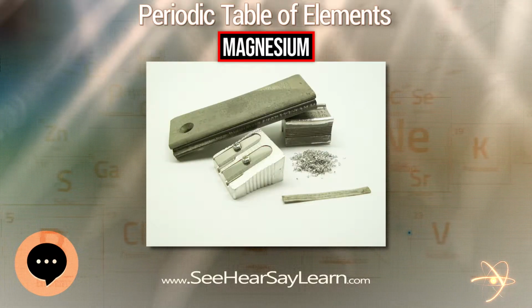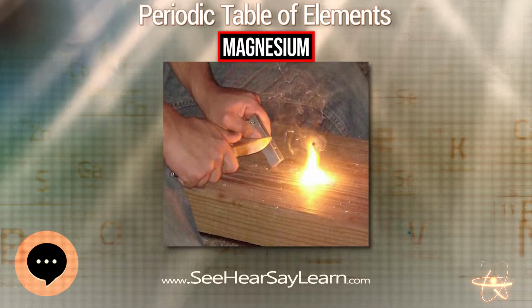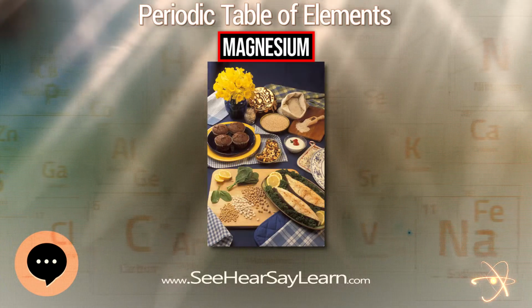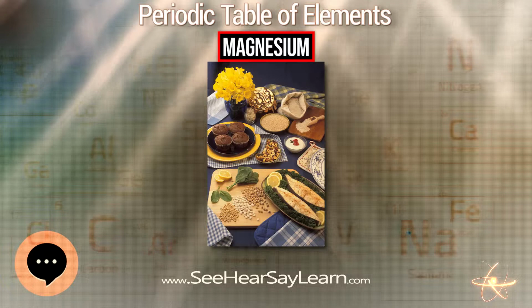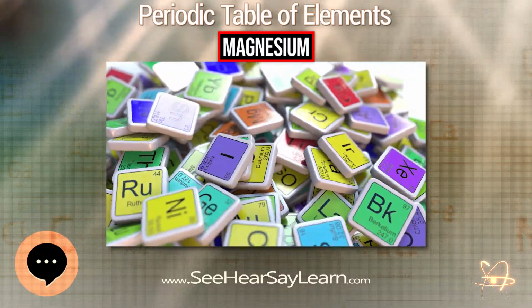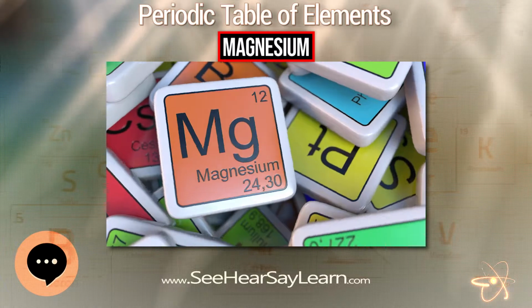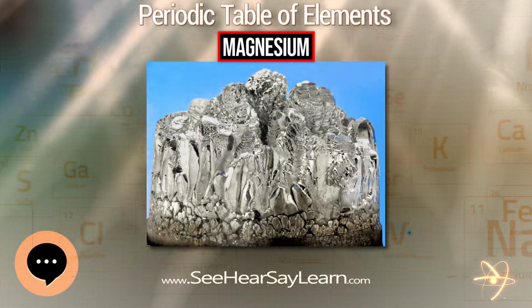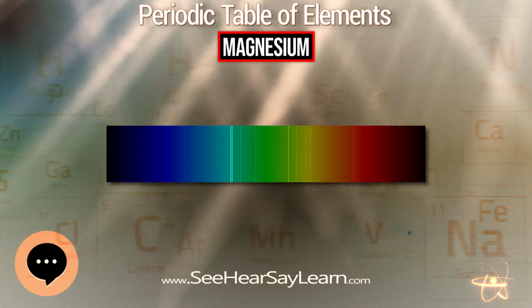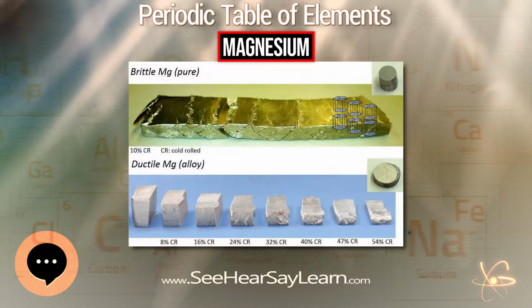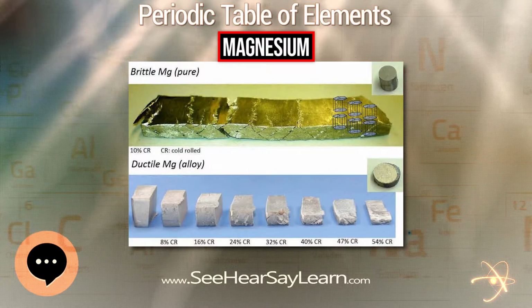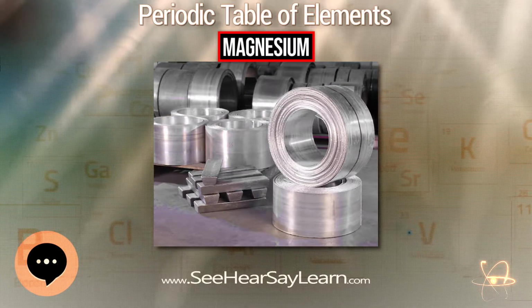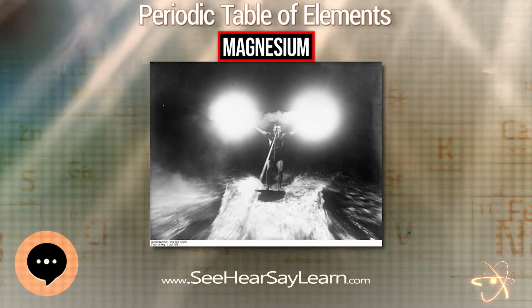Currently, magnesium alloy use in aerospace is increasing, driven by the importance of fuel economy. Development and testing of new magnesium alloys continues, notably Electron 21, which has proved suitable for aerospace engine, internal, and airframe components. The European Community runs 3 R&D magnesium projects in the Aerospace Priority of 6 framework program. In the form of thin ribbons, magnesium is used to purify solvents, for example, preparing super-dry ethanol. Both AJ62A and AE44 are recent developments in high-temperature low-creep magnesium alloys.